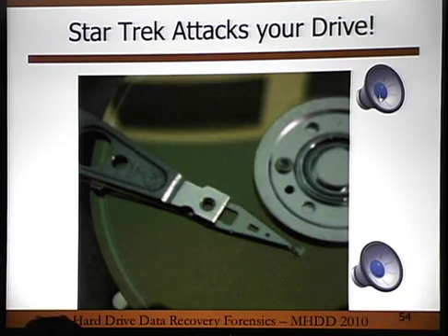Nobody's heard that? Yeah? So normally what this would mean is that I've got a head stuck to the platter, or I've got a spindle that doesn't turn, so the heads cannot read anything, so they'll make noises like this. So here's another one that you might have heard that's very similar. Anybody heard that? Yeah. So normally that means I've got a spindle that's not turning, my head is stuck.